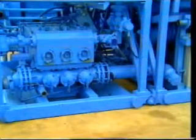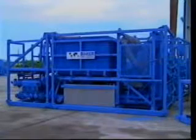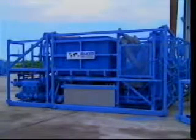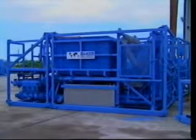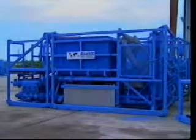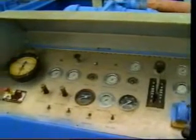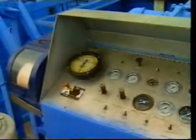The triplex pump and the equipment associated with the pumping unit are the most important pieces of equipment on location during a gravel pack operation. This unit is powered by a diesel engine delivering over 400 horsepower. Each has a maximum working pressure of 10,000 psi and a maximum flow rate of 10 barrels per minute. Located on top of this unit is the operator's control station. Here, the pump displacement and operations are controlled and monitored throughout the job.